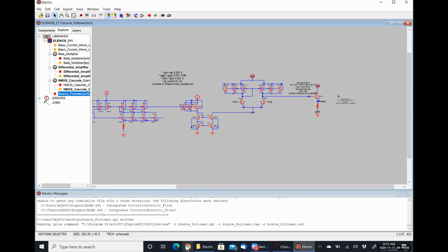So my concern with chaining your oscillatory circuit into that is that you have a circuit at a fixed frequency going into a filter, and if it's inside that filter's range, it's not going to move the frequency. Does that make sense? Okay. So yeah.